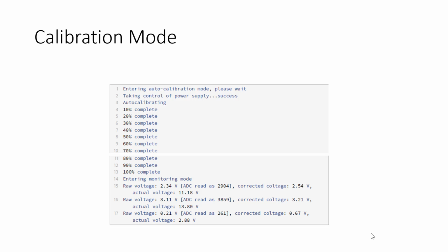Yeah, there's no way to ask the power supply if it's done, right? So you're having to do this asynchronously. 500 milliseconds would be a good place to start. Yeah, about half a second. You can go longer if you want. You'll have to experiment, because there's no way to handshake with the power supply and synchronize. It would be nice if the power supply would acknowledge when it's finished changing, but it doesn't do that, right? Okay, yeah, so you'll have to put a delay in after you change the voltage.